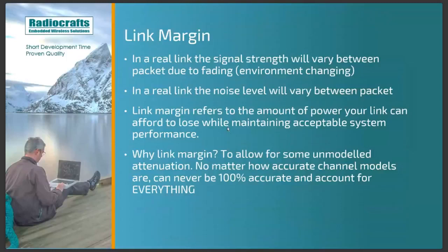This is how the world is in an indoor environment. People are moving, doors are being opened and closed. So the environment is never static. That means when you set up a link, you need to make sure that you're not just at the edge of where you can operate. Also, the noise level, as we saw above, is very much time varying. It can vary over a day, or it can vary from second to second actually. So when you set up a real link, you have to consider these elements and actually choose a lower range than the maximum you can have.